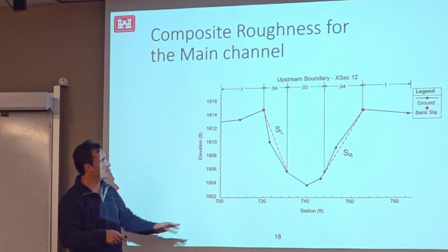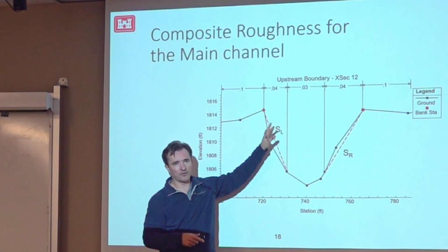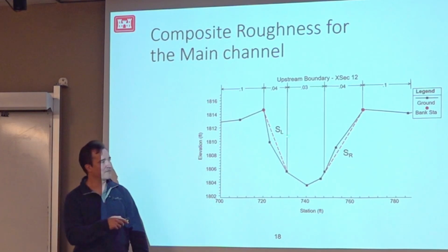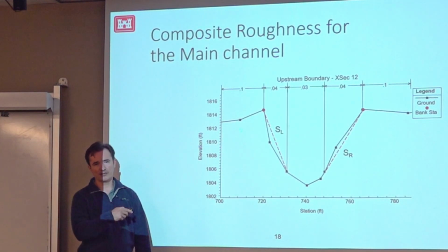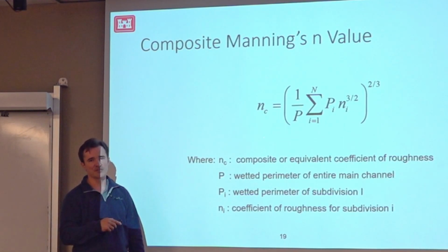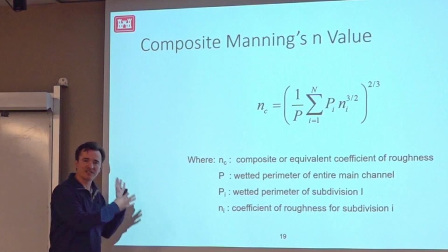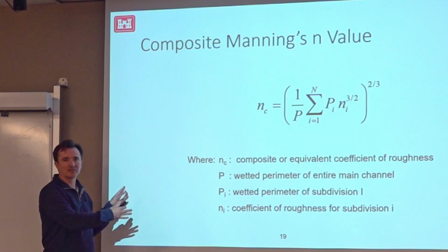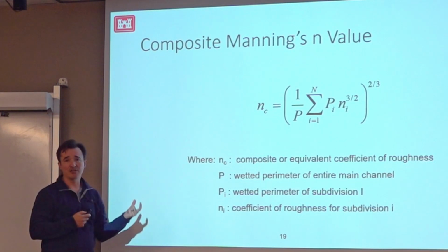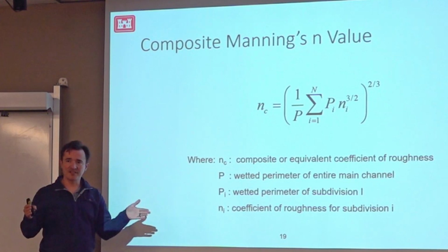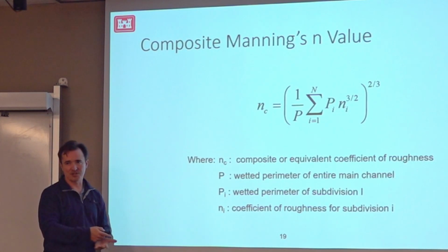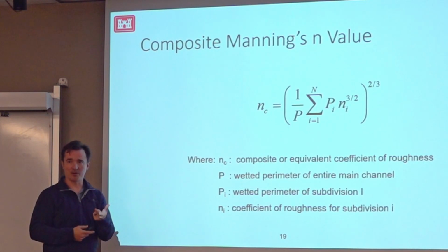It's more realistic to assume a constant velocity for the whole channel and compute a composite Manning's n value, even if it's varying along that channel. This is how we compute that composite Manning's n value inside the channel. The overbanks you can divide if you have variable Manning's n, and it splits them into smaller conveyance components, right? But the channel doesn't. If you have variable roughness inside the channel, it's going to compute a composite Manning's n for the channel and compute only one conveyance component.